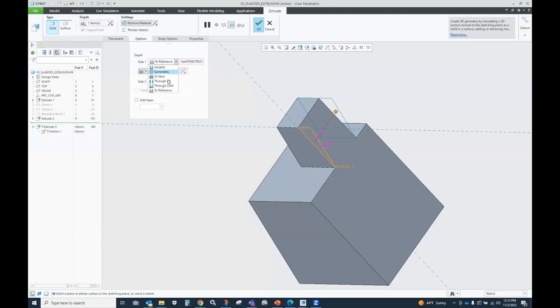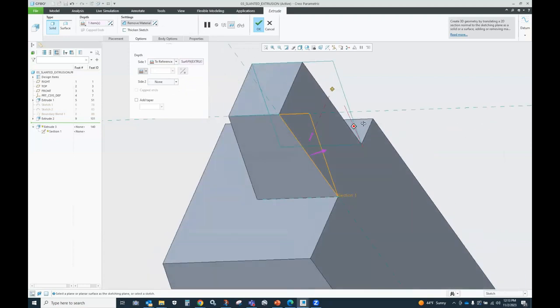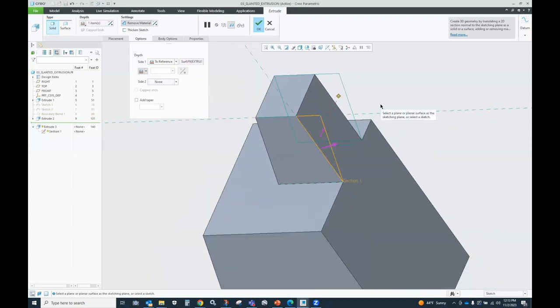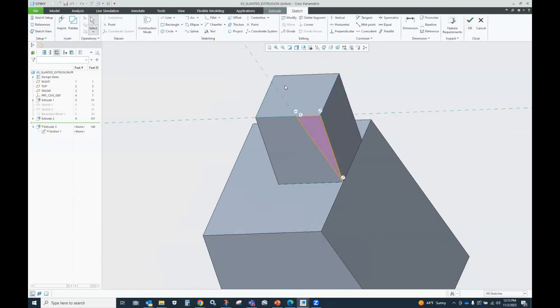All right, so these choices are pretty important because they are references and they're going to determine how robust your model is. Okay, now what's the other thing I could have done better in this case? The open sketch, right? I don't need this piece of geometry or that piece of geometry. They have IDs associated with them, and I already said, fewer IDs equates to fewer failures. So don't create something you don't need.